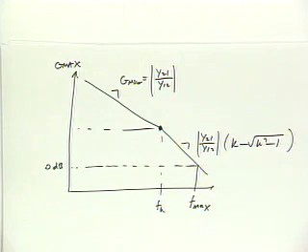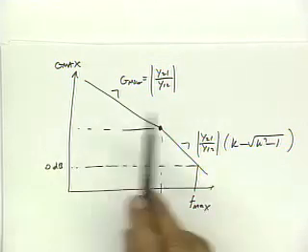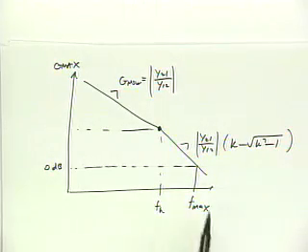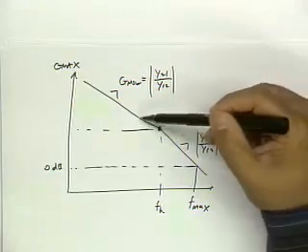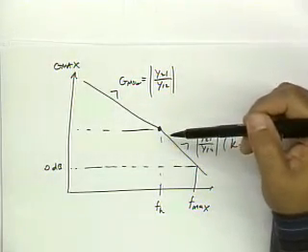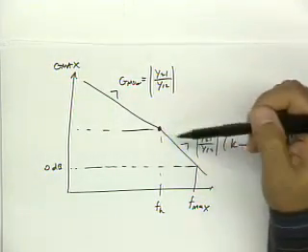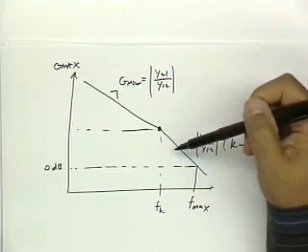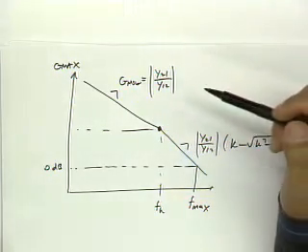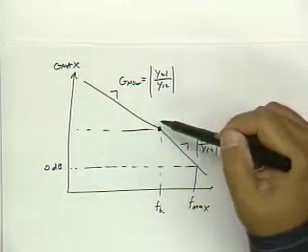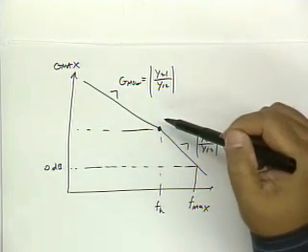Okay? So this very common way to characterize a transistor is you plot these various quantities, and this curve does represent the maximum gain you can get out of the device if you're just willing to change the source and load impedance, right? If I'm just willing to change the source and load impedance and to have a stable amplifier, this is the maximum gain I can possibly get.